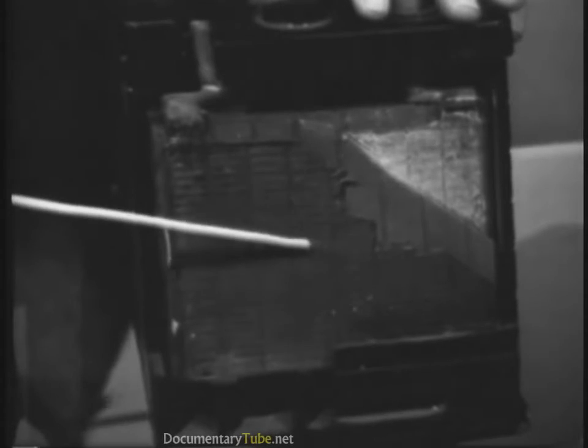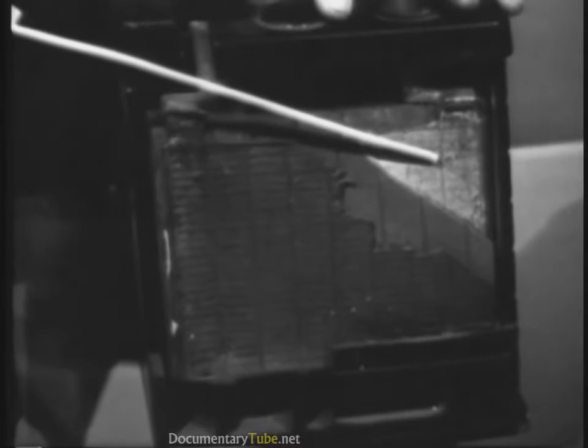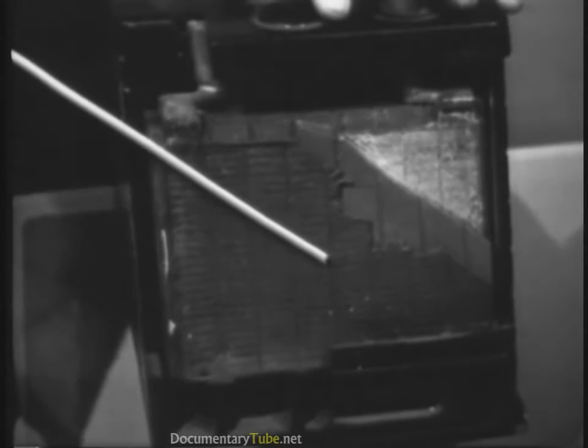A car battery is another example of developing the voltage by chemical means. In this case, the electrolyte is sulfuric acid diluted with water. The electrodes are sponge lead here and lead dioxide here with a separator in between. Basically, this battery develops voltage in the same manner as the dry cell. The chemical reaction will cause the lead dioxide to become positive and the sponge lead negative, so voltage will exist between the two.